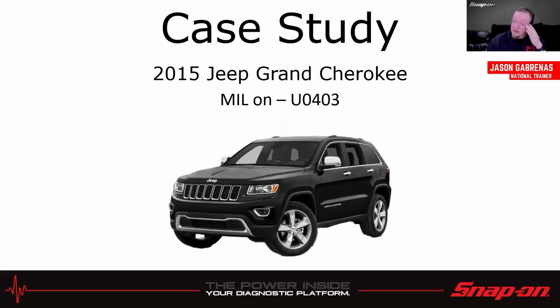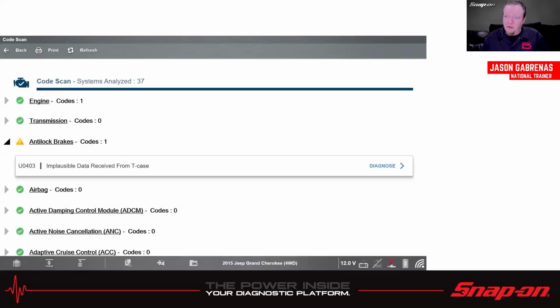So now we have a little case study to talk about bus problems. And this one's a little unique, and I think it's a pretty good story about that. So this is a 2015 Grand Cherokee with a U0403 code. So that's a communication code with the transfer case. So it says implausible data received from transfer case. And usually this doesn't throw in the engine, this will throw in the ABS or the transmission usually.